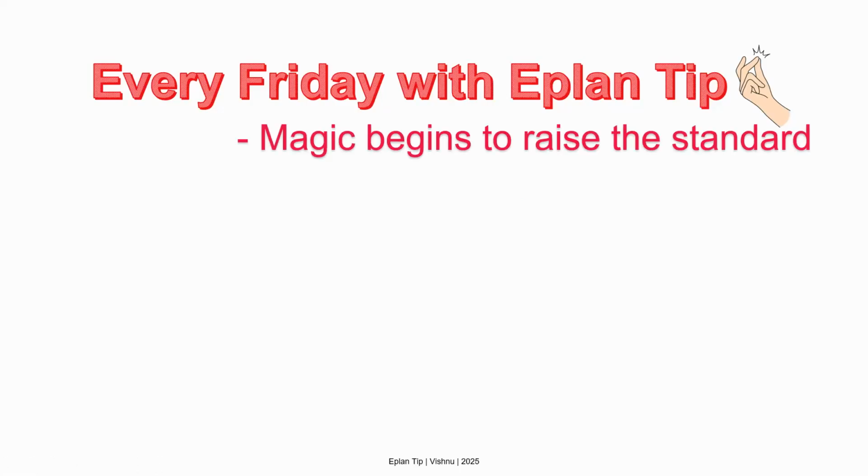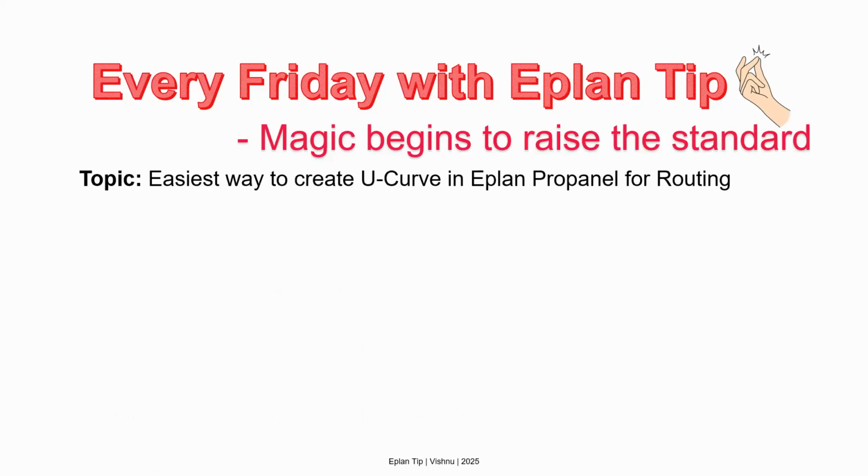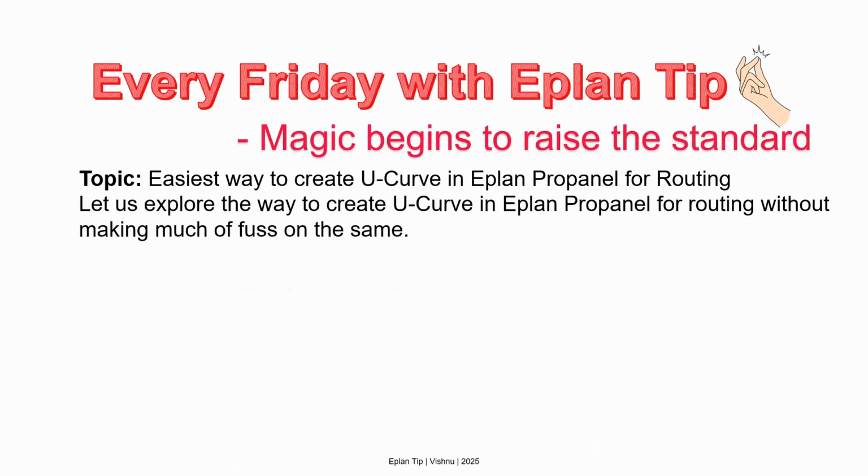So, what is today's topic? Today's topic is we'll go into 3D. Especially for us, the challenging part is always drawing the U curve. Is there any easy way to create a U curve in Eplan Pro Panel for routing? Okay, let us explore how we have to draw this U curve.